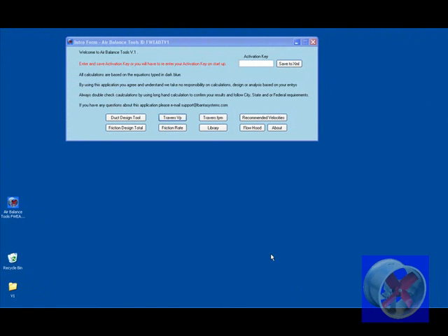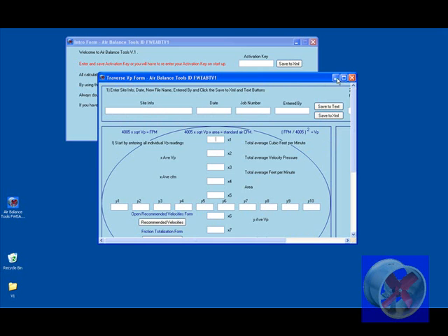Okay, now we've had a good refresher on a couple of calculations related to airflow. We just got a task that we had a 3-story building, and this 3-story building has a major pressure issue, and we have a transmitter that went out on a Paragon air station. It's a 4 to 20 milliamp. It sends a signal to a DDC system, and we're going to have to go out and troubleshoot it.